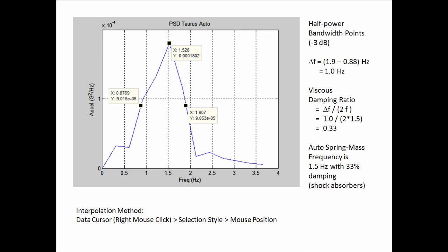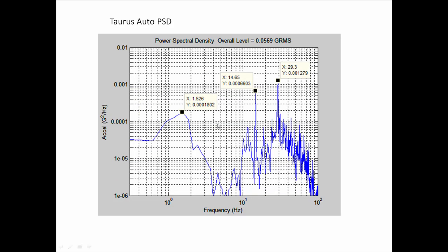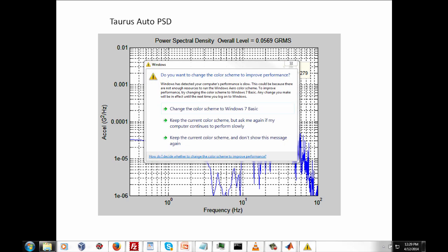So let's go back to our data. And it looks like, in fact, yes, we do have a 14.6 hertz spectral peak there and a 2 times harmonic. So these two spectral peaks are almost certainly due to the tire imbalance effects. And the significance of that is if the car were going slower, these spectral frequencies would drop, or if the car was going faster, those spectral frequencies would increase. So it's important to know which of these peaks might be changing under different conditions. We'd certainly expect that change to occur.